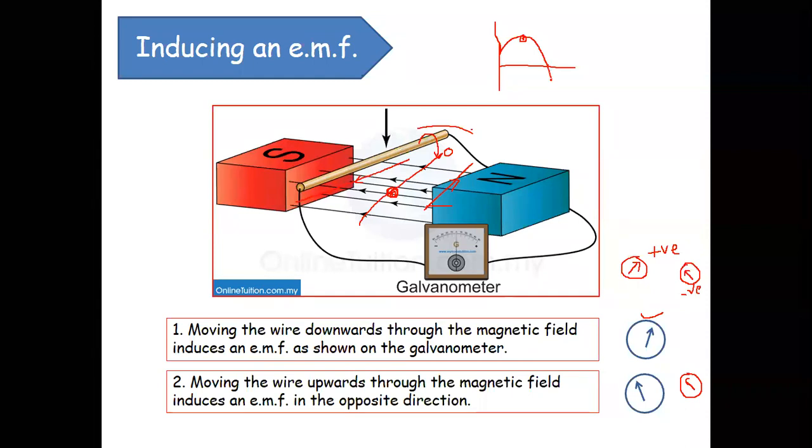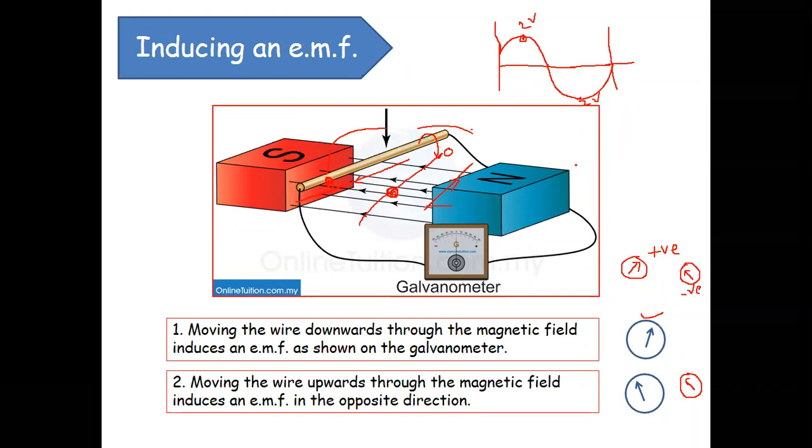Now once you increase to 135 degrees, your conductor will be coming directly under south pole. So negative voltage, negative max. When you rotate further, the conductor reaches once again the magnetic neutral axis. So for one 360 degrees mechanical rotation, I can get one alternating EMF waveform. So this is 2 volts and this is 2 volts. So we can say the EMF developed is 2 sine omega t.